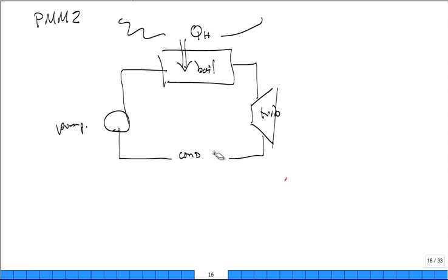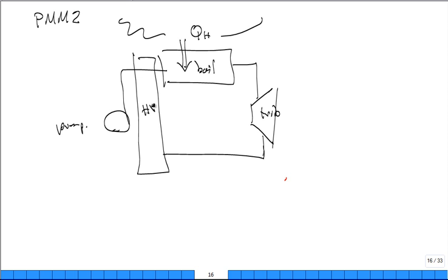I'm a clever engineer. So I know that I need to condense the steam, but I also have to heat up the water after the pump. Heat exchanger right here. This is a great place for a heat exchanger so that I will be able to condense the steam right here. So this will be liquid coming out. It'll be condensed. And it'll preheat the feed water before it goes into the boiler. Smart! I'm a millionaire.